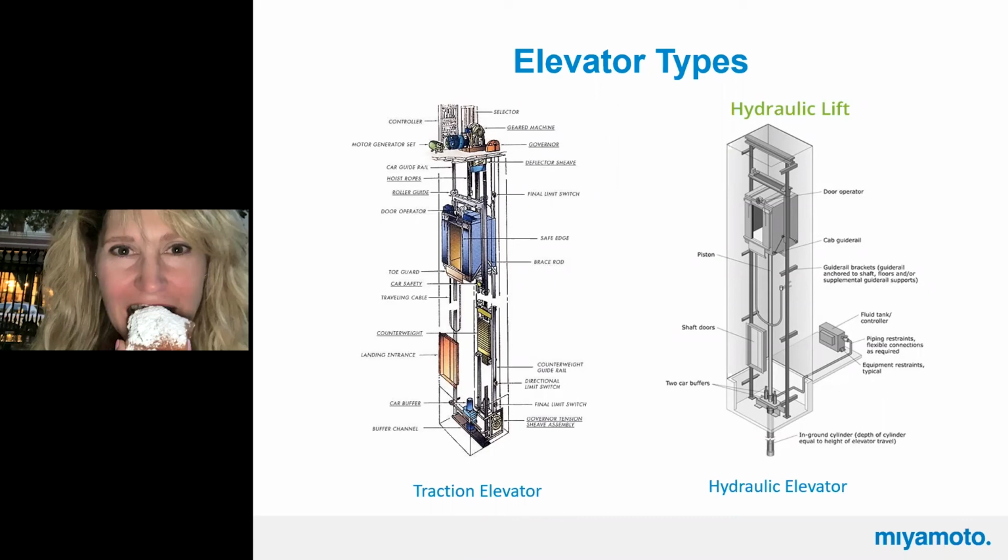Something else that I have noticed is where we place our rails or halo steel around this thing as well. Because you were talking about the fire requirements, you do want to look at the architect's detail to see what he's doing, because they're going to look at our drawings to see where to place those elements. I try and drive them to look at the architect stuff, but you do want to coordinate that with what you're trying to do with your wall and your slab and how that's working. It's not just throw those elements on your plan.